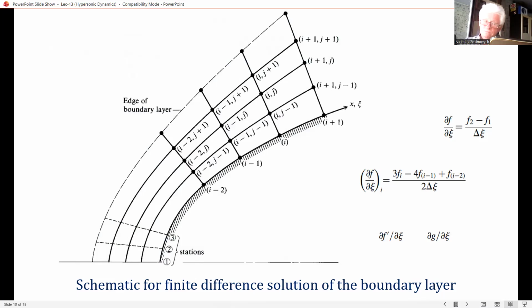The boundary layer solution at this location can be obtained from the self-similar solution discussed several lectures ago. Moving to the next downstream location, station 2, the differential method can be implemented, but with 2-point one-sided differences for the zeta derivative, as you can see here on this plot. Moving to the next downstream location, station 3, the full method, as just described, can now be implemented. In this fashion, the complete non-similar boundary layer over the whole body can be calculated.